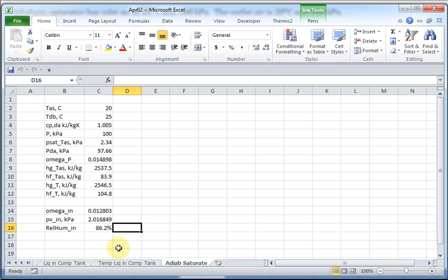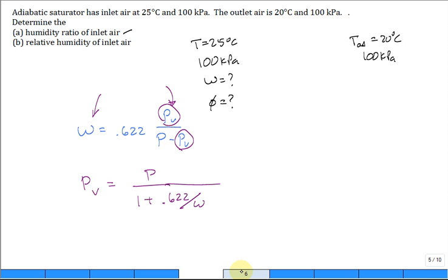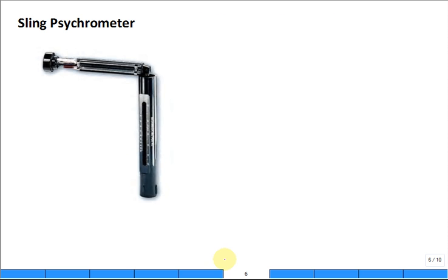Okay. So I said that this adiabatic saturation temperature is the same as a wet bulb temperature. Temperature adiabatic saturation is the same as the temperature wet bulb. The temperature wet bulb is really easy to explain. You just need a sling psychrometer, and here's one right here in the box. And what you do is it has two bulbs. One is dry, it's just exposed to air. One has a wick over it. And every semester I got to put a little water on the wick, and so you can feel it. I'll pass it around, and so it's moist.